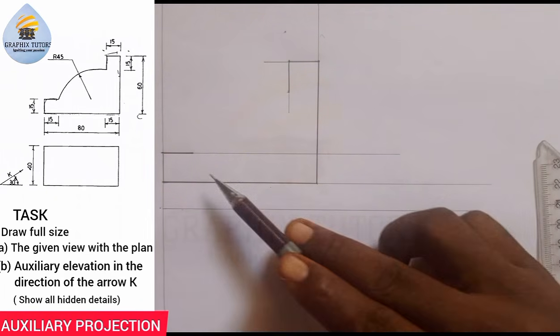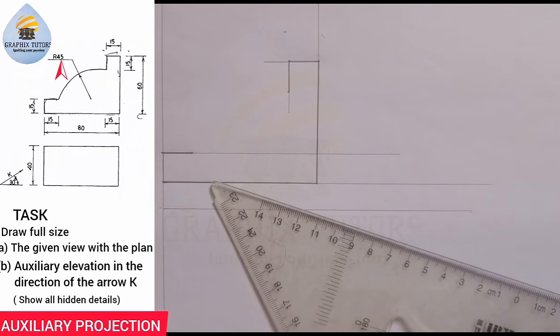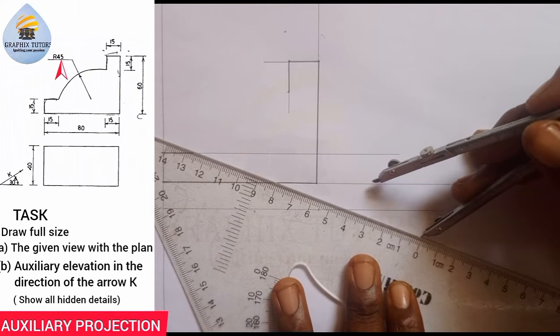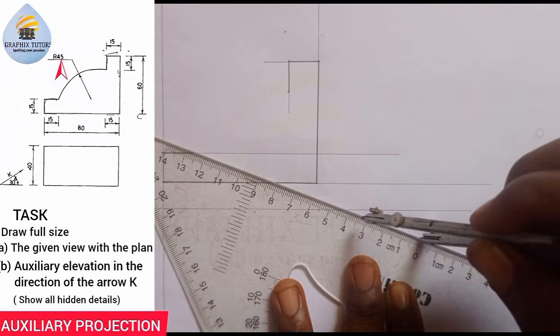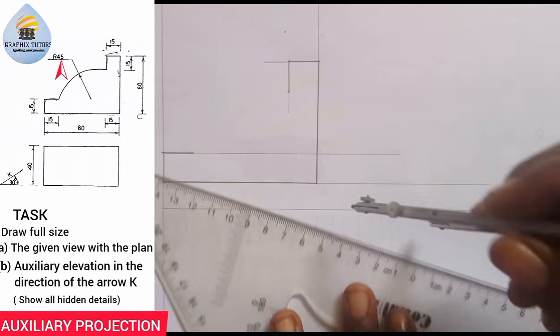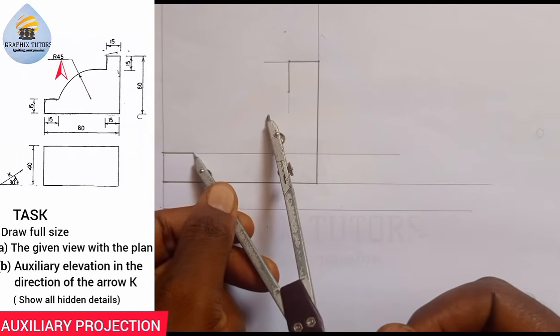Now the next thing is what? The curve we have here, as you can see, and that's the radius of what? 45. So it is easy to do it this way. Just take your compass and you measure 45 from 0. This is 45 here. Hope you can see that. And I'll place it at this end here where the curve meets. I'll strike an arc here.